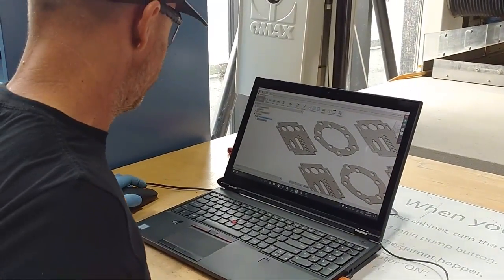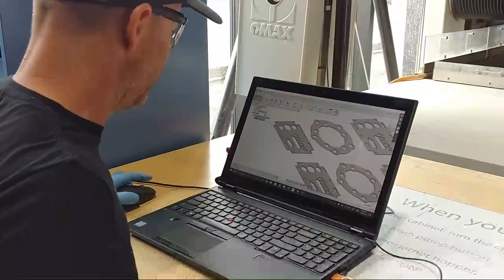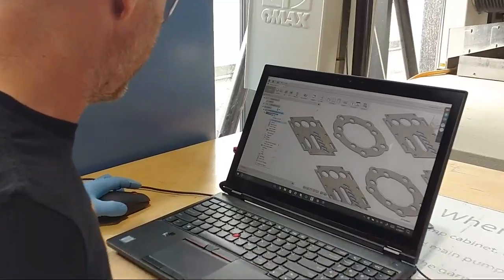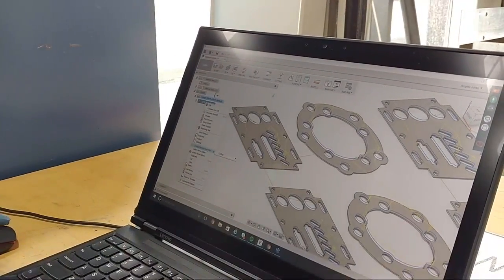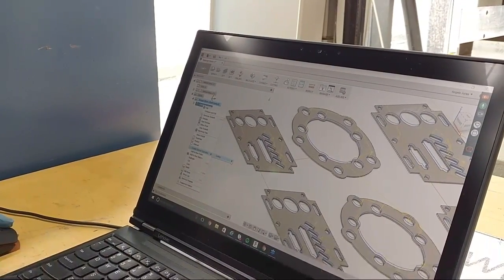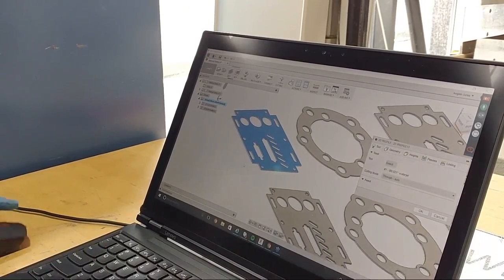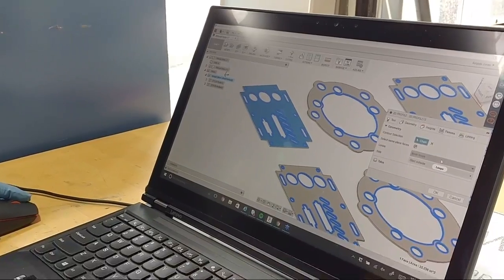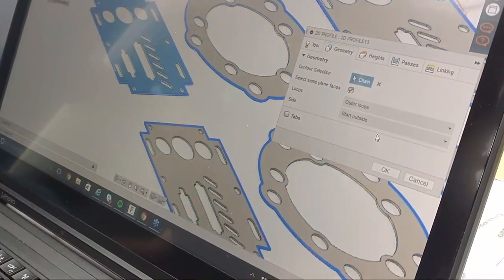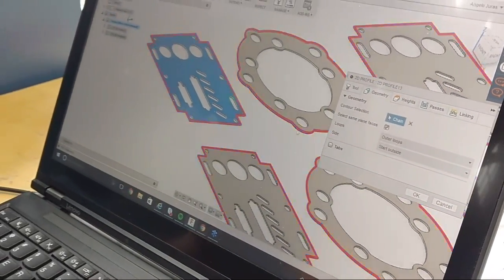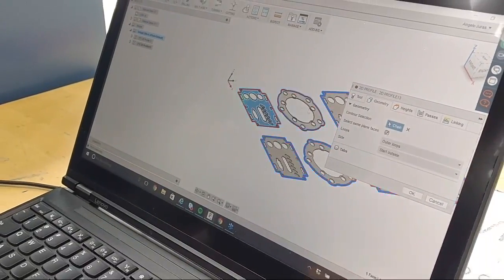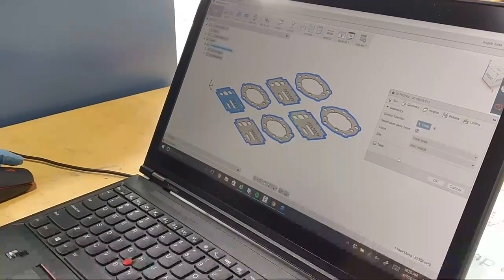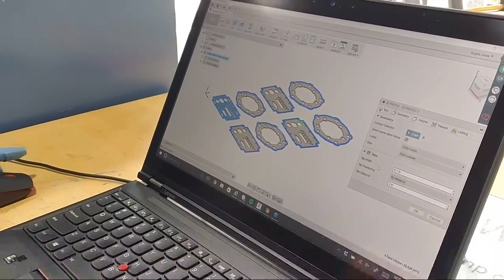All right, so we can do a couple of ways. We can derive a toolpath. I'm just gonna do that. I'm gonna do create derived operation, cutting 2D profile. On the geometry, all I'm gonna do is outer loops, and look, everything is selected. Just a couple of clicks. Because he did that derived operation, select same plane was already picked. That's correct. Let's add some tabs in there.